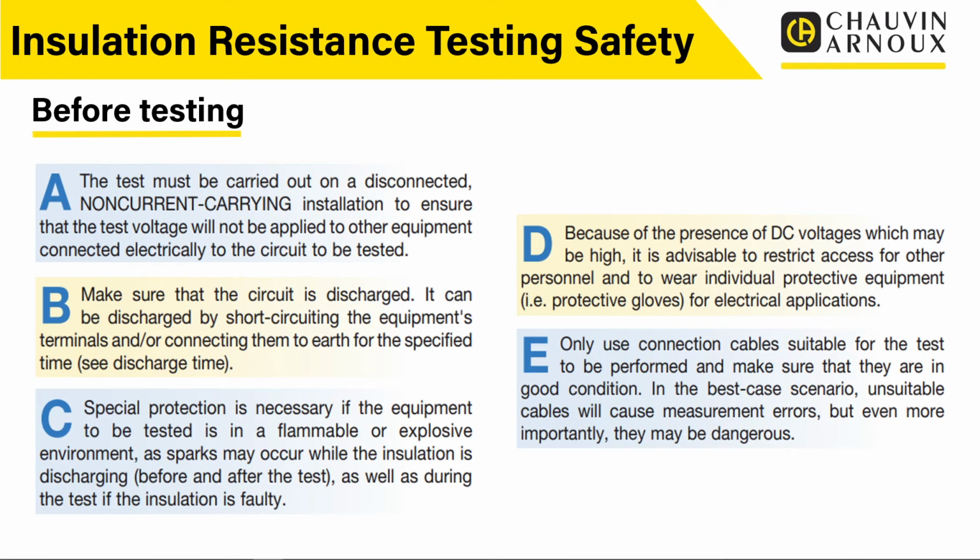So always consider that. And if you are carrying out testing in any areas like petrol station forecourts, for example, you need to be well aware of the precautions. And obviously, if in doubt, just don't carry out that test because it could be potentially disastrous.